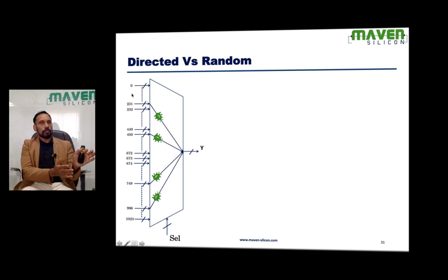We have run simulation for more than 1 hour. The question is, did we find any bug? And in this case, how many hours would it take to reach all possible values? It's going to take more than a week. But no one is going to give a week to verify a simple multiplexer. Maximum you may get 8 hours. So within 8 hours, how best can we find all possible bugs?